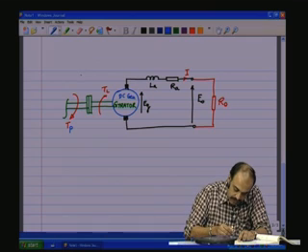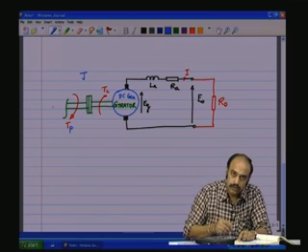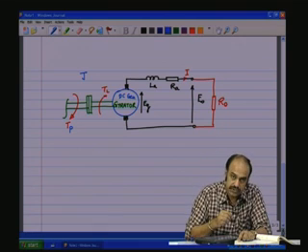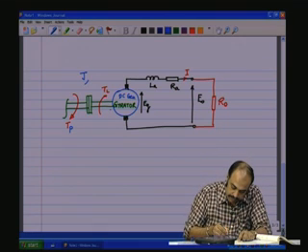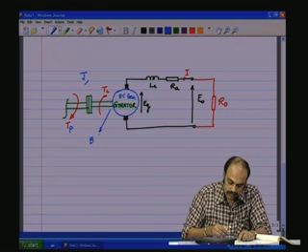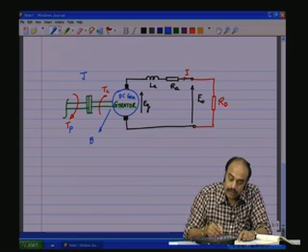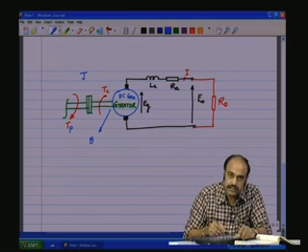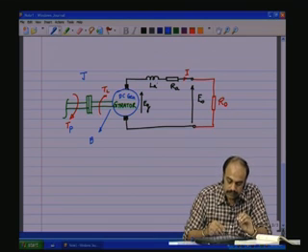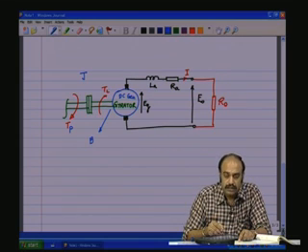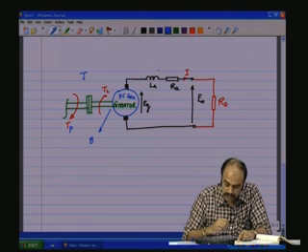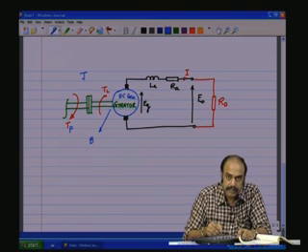Now, the shaft has an inertia, reflected inertia, including all the things that are coming from the prime mover side, which is J, and there could be a bearing friction B on the mechanical side, and on the electrical side we have LA, the armature reactance, which is represented as an inductance LA here, called the armature inductance, which we use for the dynamic model. In the steady state model, that does not come into the picture because DC currents are flowing and the induced voltage is 0 there, and RA is the armature winding resistance.